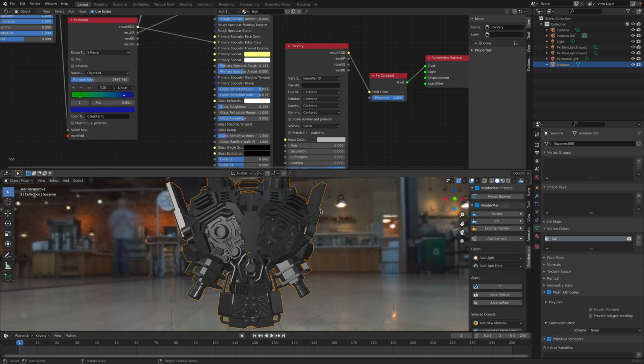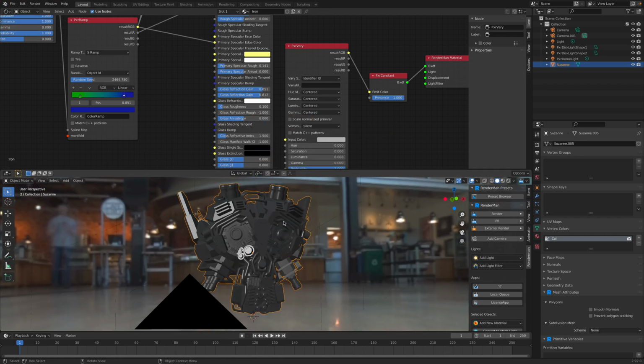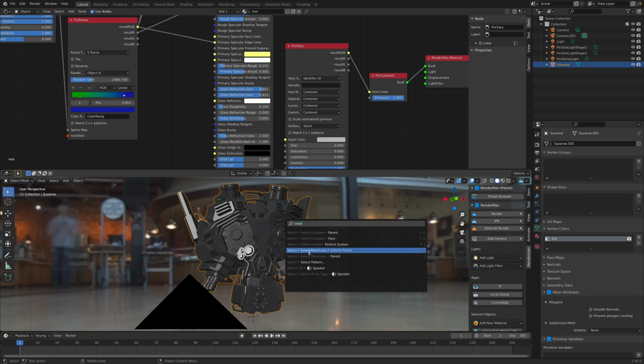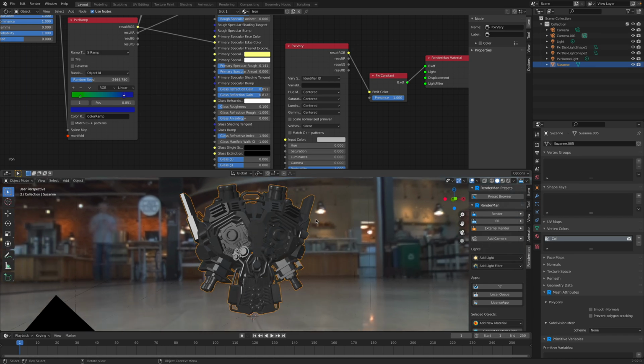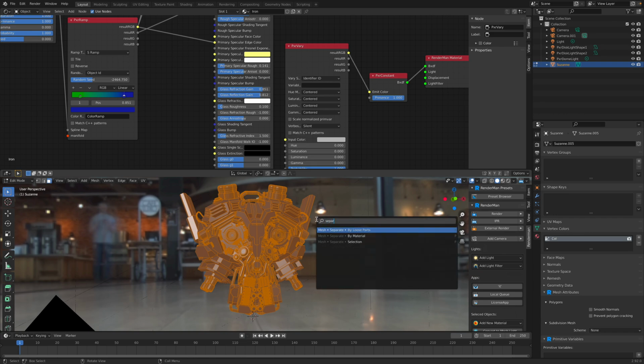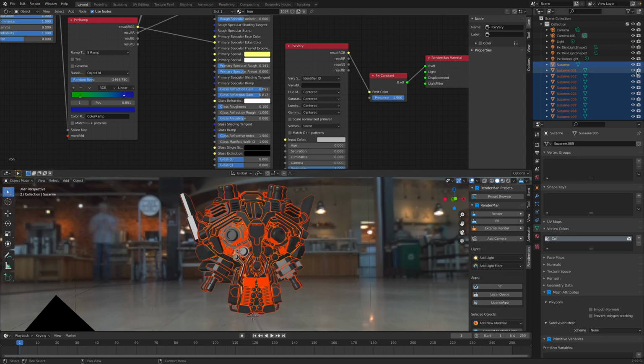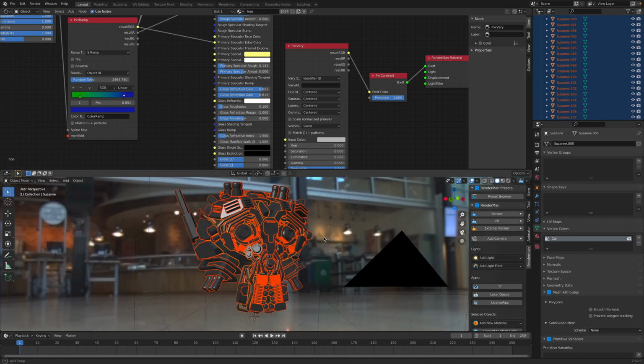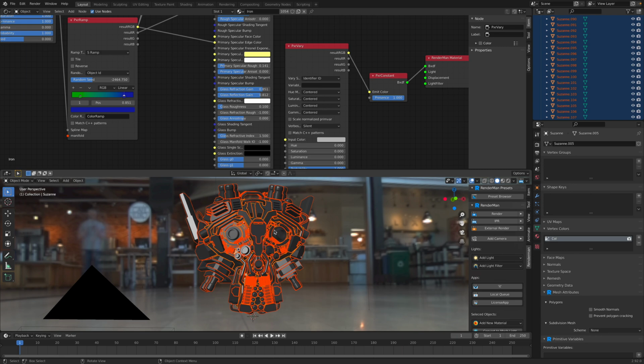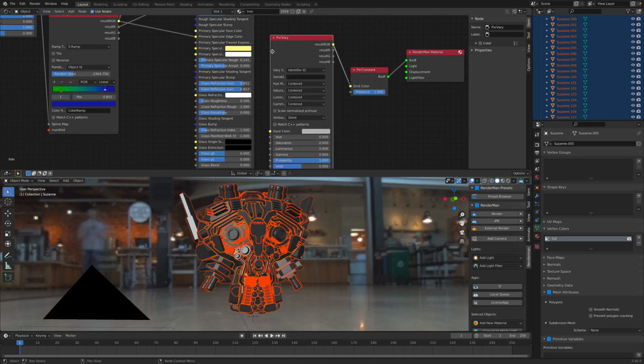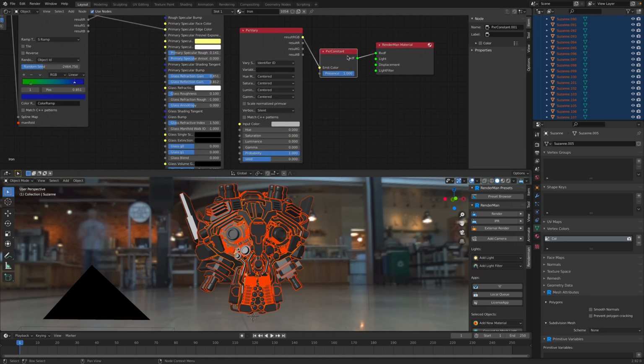This is PxrVary. If I want to separate this, this is Blender 2.92. I think I can use F3. Oh, it doesn't have separate every object. I need to go to Tab and then separate by loose part here. Now how many objects do we have here? We have a lot of objects, right? These are all the separate parts. I kind of want to randomize this as well. You can randomize it the easiest way, maybe using Python, and randomize using different materials. That's also something to try. But I want to give it the Pixar varying color. I have an old video talking about PxrVary. It's kind of similar.